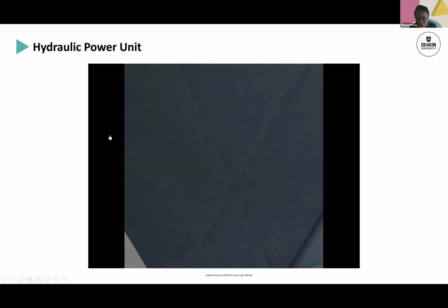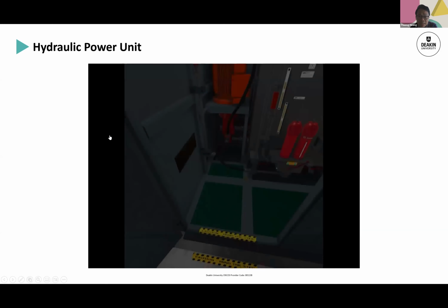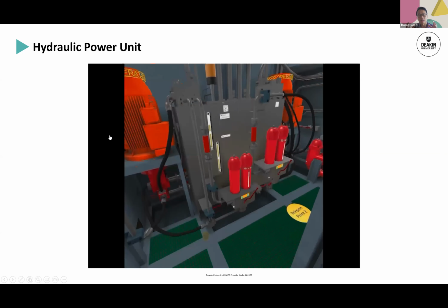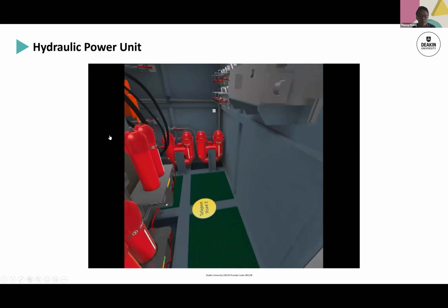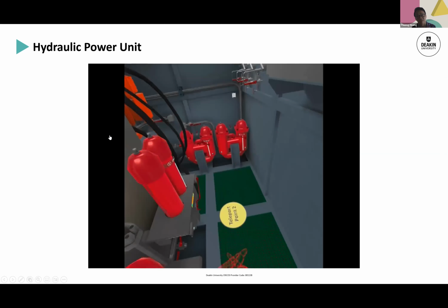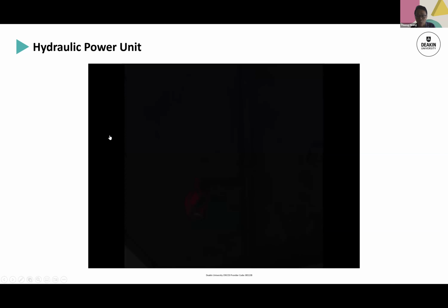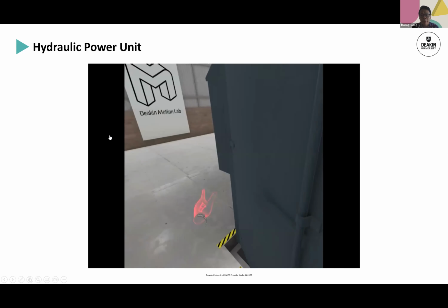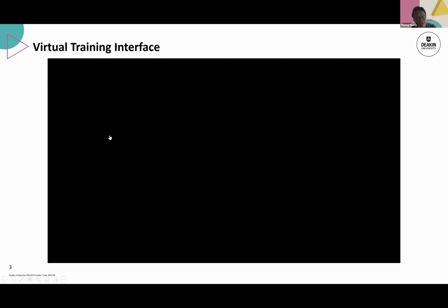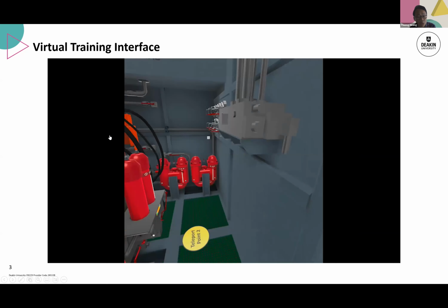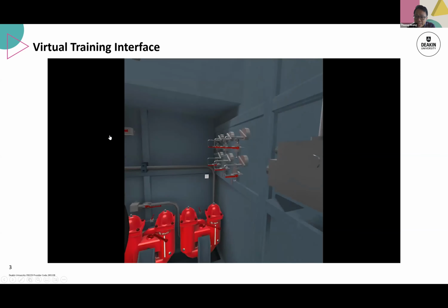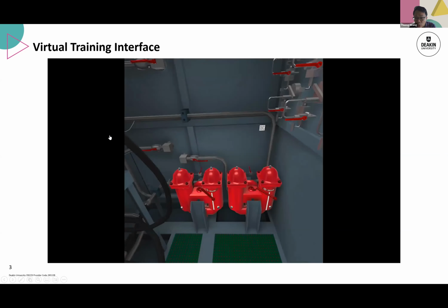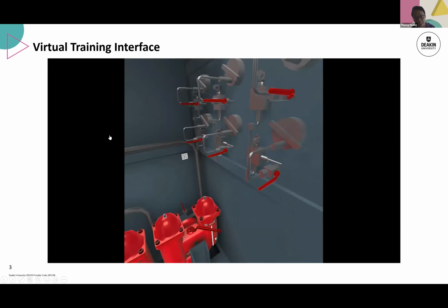This unit is quite large, about 5 by 2 by 3 meters, because our client is building this for their mining industry partner, where they use the whole machine to flip the whole train carriage of iron ore over. We were given a digital twin version, a virtual model of the machine, and we did model simplification using Houdini because our target platforms are Quest 1 and 2. They have very limited processing power.